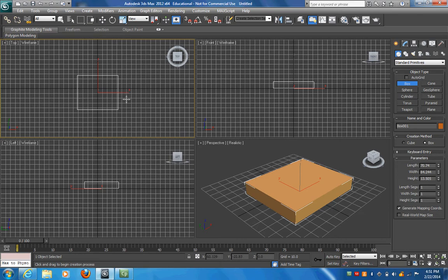Now, my box is going to hold my imports for my inlets for my jet. So I'm going to configure this. What I need to do is basically have my width and length segments of 3 by 3, and then I'm going to leave my height segments as 1. So when I click on and see my 3 by 3, you can kind of see my segments set up like this.